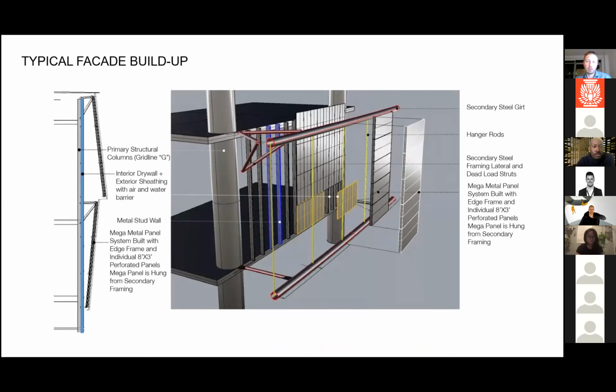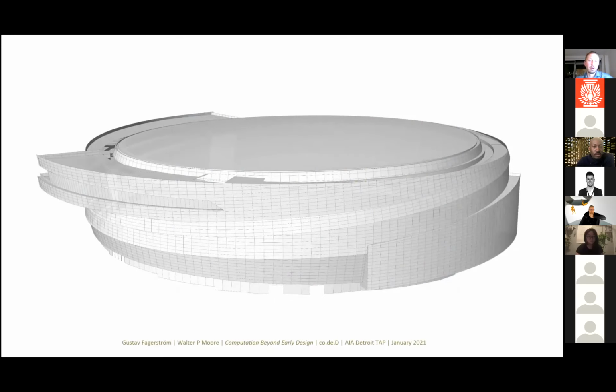So that is a flat plane, right? Each of these is a planar object. When you are analyzing a curved shape like this, if, for reasons of architectural design intent, your panel joints can't always trace the plank lines of the ruled surfaces, then you get curvature in your panels, which you don't want, because then you're going to have to start curving your mullions and your metal sheets and whatnot.